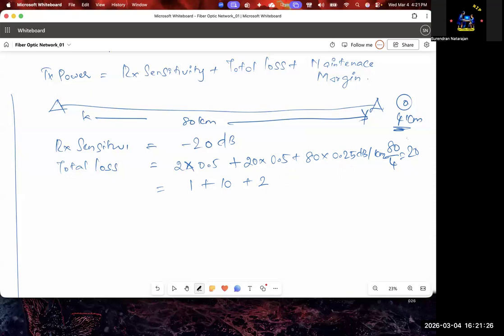We put 0.25 there. Yes, Harish, this is attenuation, we discussed it. Every kilometer the light travels, it loses 0.25 dB of power. We said 0.2, right? Is it 0.25 or 0.20? Okay, whatever value, we can change it now. I will give the reference values once again.